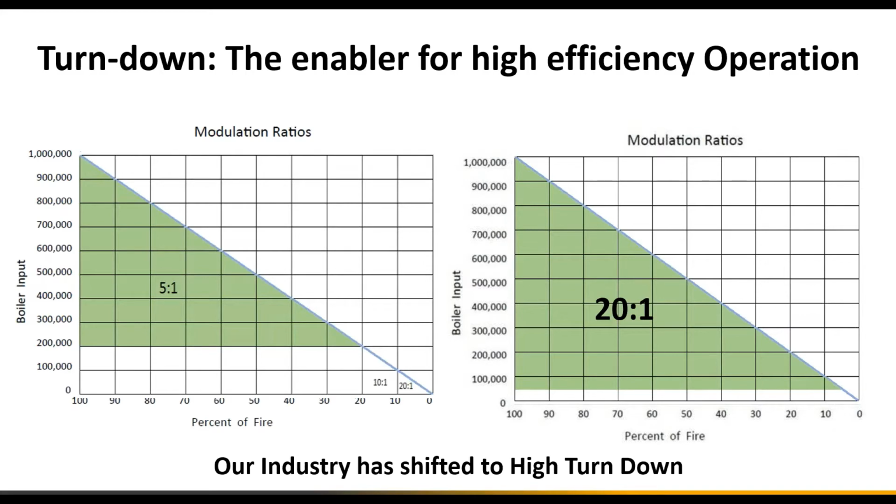Looking at outdoor temperature, looking at system supply temperature, the plant itself very carefully delivers just the right amount of BTUs that the system is asking for. And as demand increases, the firing rate increases, and if necessary, additional boilers come on to satisfy the load. Moving on to the next slide.